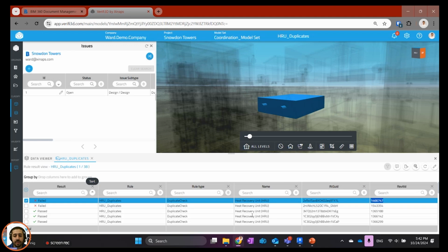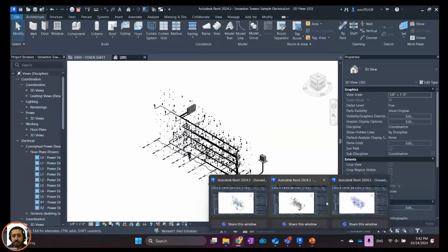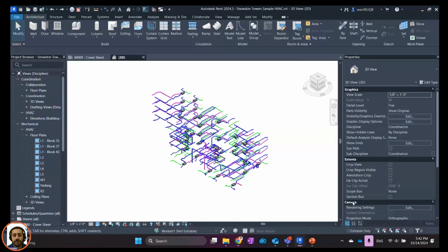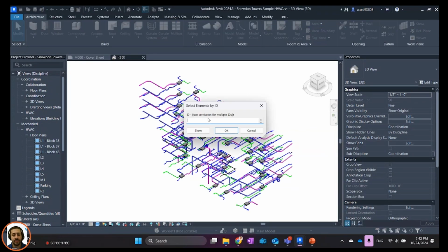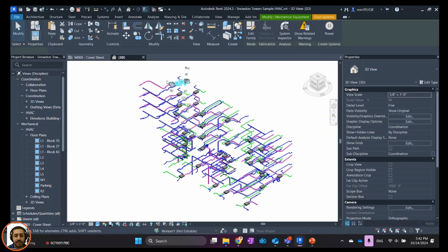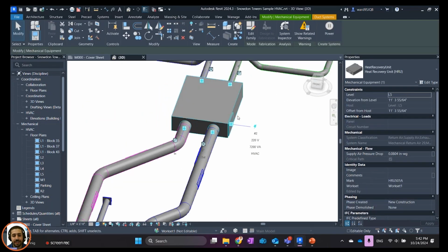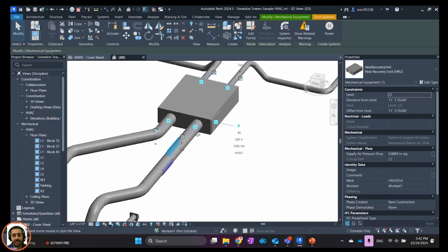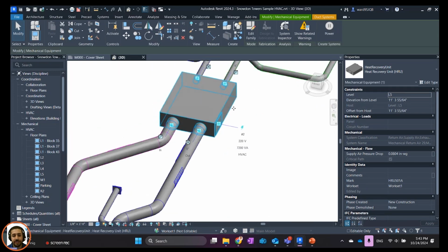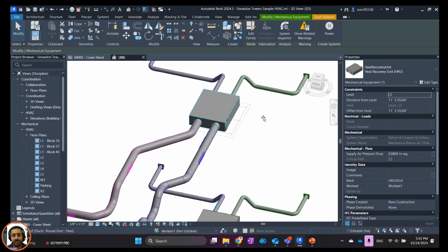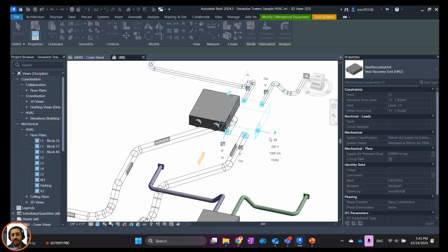So I'm just gonna copy it from here. Okay, and then I'm gonna go to my Revit account. So this is the mechanical one, which is this one. There you go. Then I'm gonna go to the ID, select the element. There you go. Yes, as you can see, even from the shape, like the shadows that exist, we have some kind of a duplication over here. Okay, so I can just select it and drag it. Yes, you can see that it's actually duplicates.